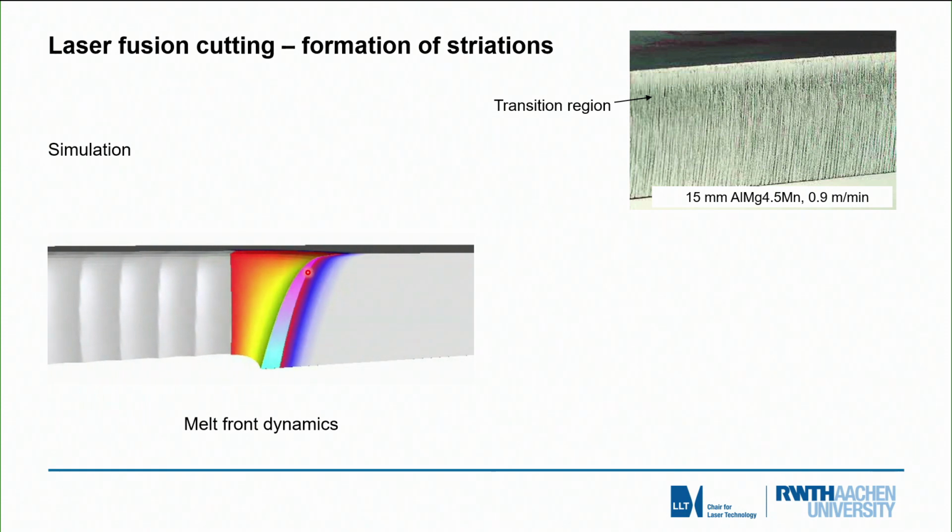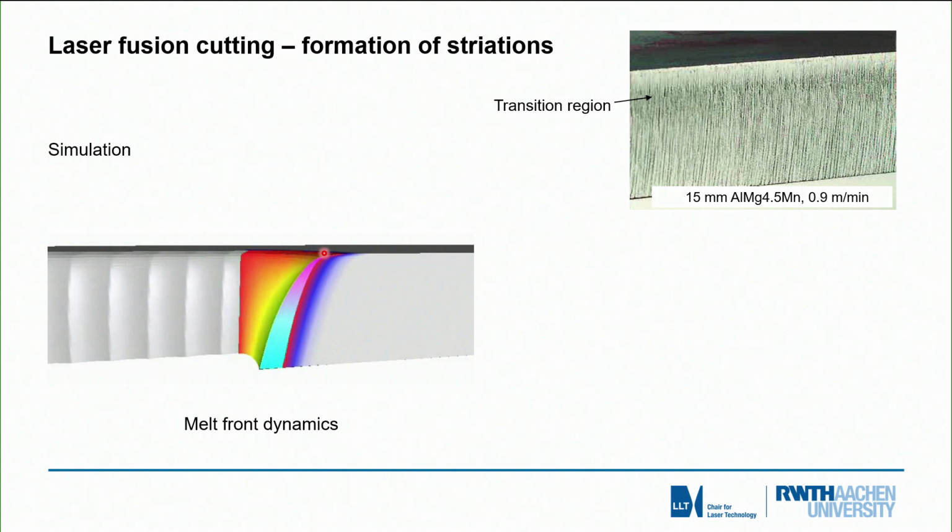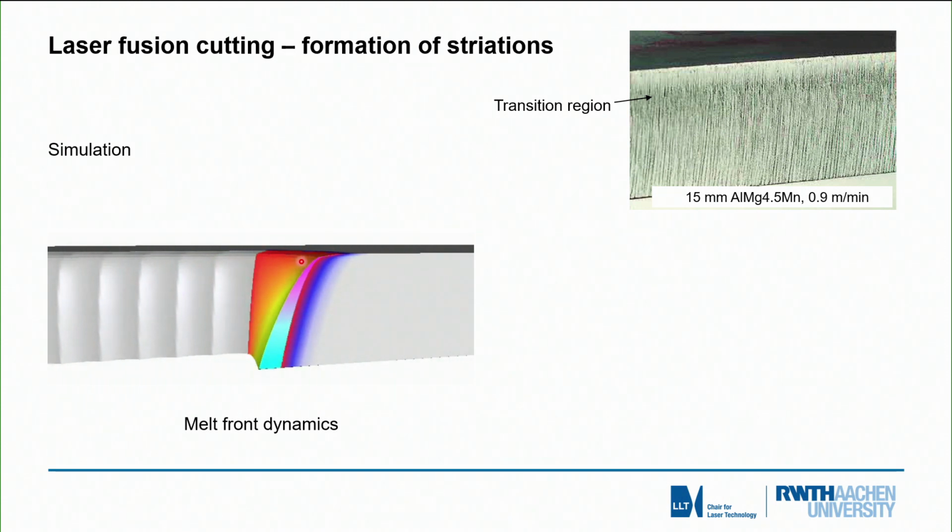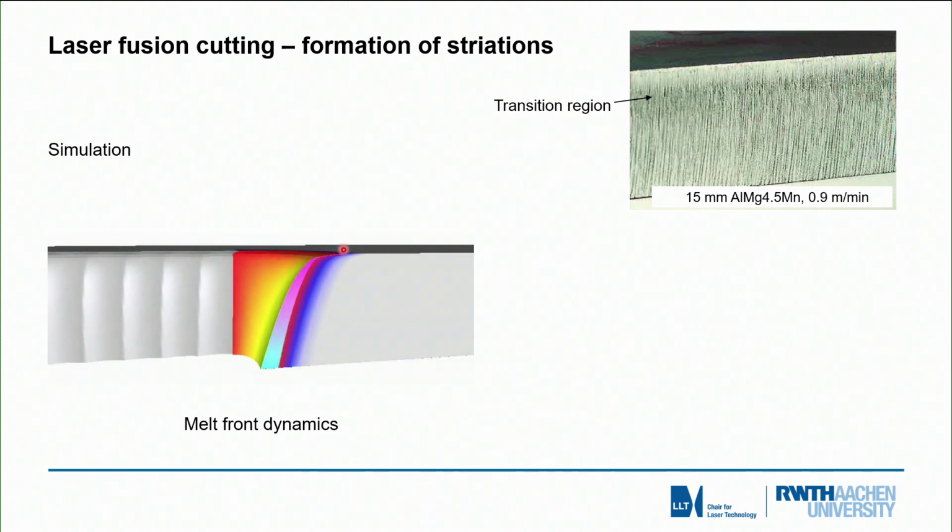The laser radiation hits the cold part of the workpiece to be cut right here, and then of course it starts to form a melt film. This melt film is very thin in the beginning, so the surface tension exceeds the force that is needed to blow out the melt along that back of the cutting curve, so it will still stick here.